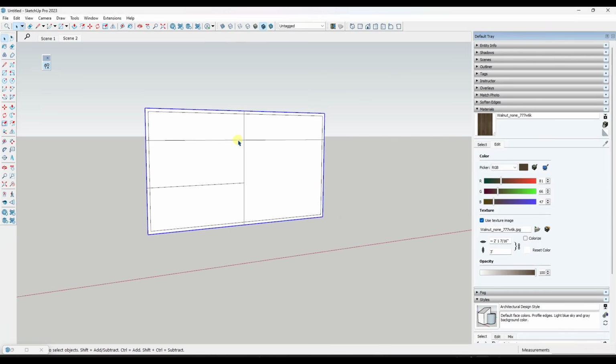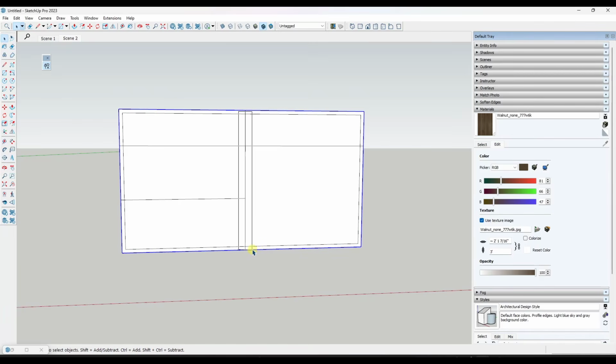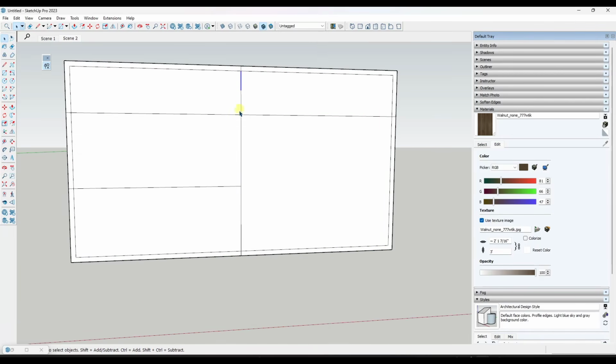And then what we need to do is we need to do that same thing for the interiors, which gets a little bit trickier. But what we can do is we can select these edges. And so what I'm going to do is I'm just going to come in here, and again, we're just kind of splitting this up so that we have a piece of trim in here, but this is going to go 3/8 of an inch this way. I'm going to use the move tool in copy mode and create a copy 3/4 of an inch this way. And then we'll do the same thing here,